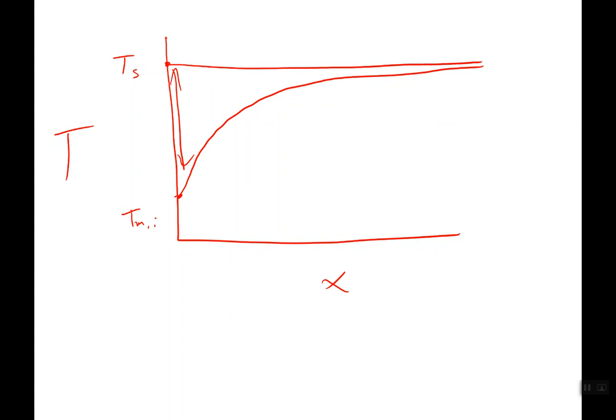So what this might mean from a practicality point of view is, let's say you want your fluid to be heated and you create this really, really long heated pipe and you maintain its surface temperature. There's going to be a point of diminishing returns where making that pipe longer and longer and longer isn't going to do very much for you, because the maximum temperature your fluid could reach would be the pipe surface temperature. Okay, I know that was sort of the last couple of lectures condensed down to just 5 minutes or so.